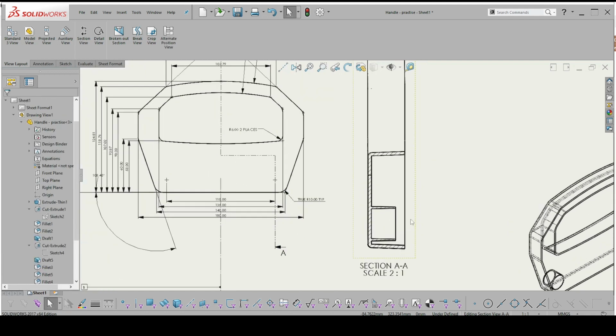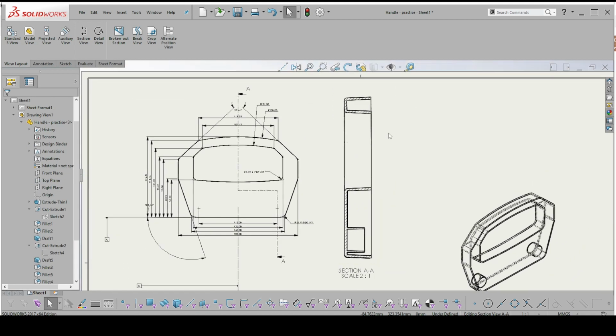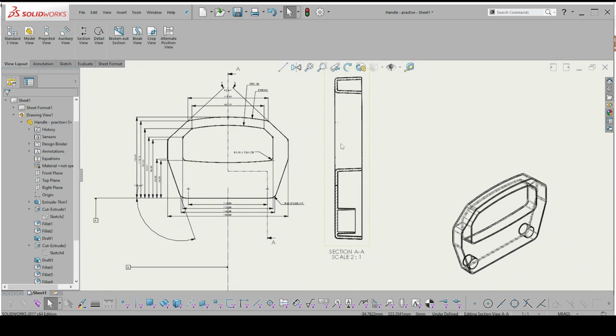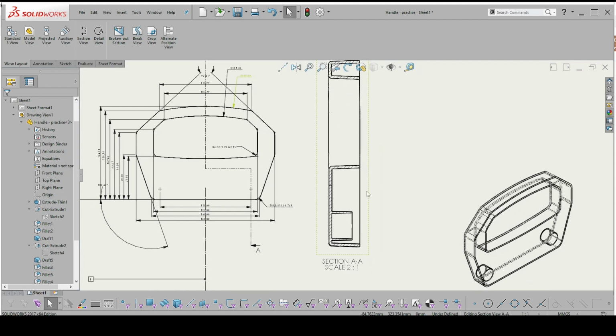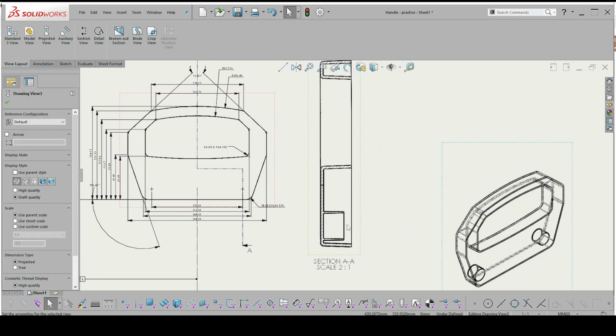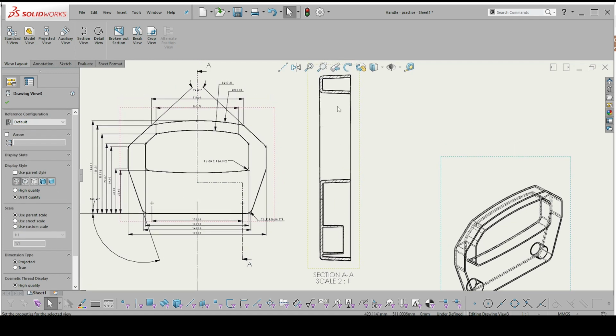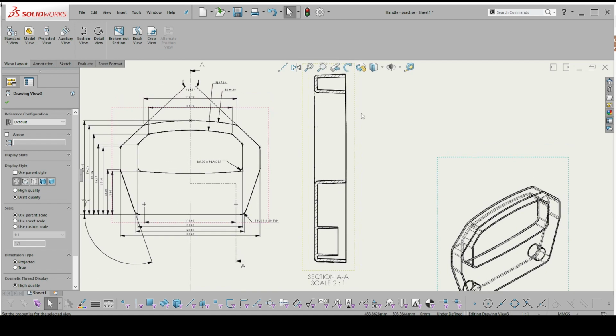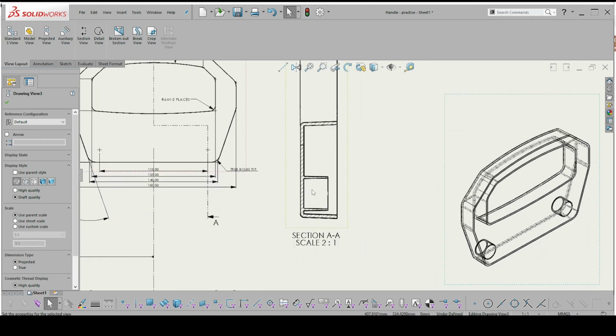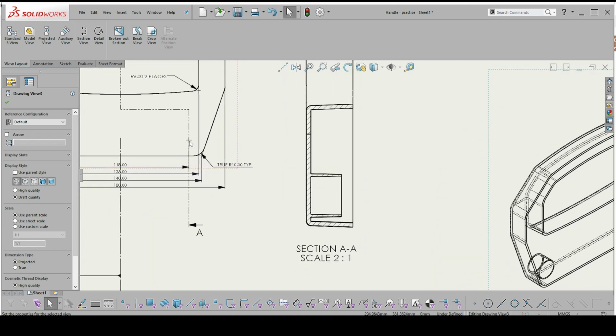Okay, so in this one here, there are a few dimensions I can get out of it. They are these edge fillets here, the center of this boss and its diameter and its root thickness, and that's about it. Oh yes, and the height. So the first thing I want is a center line here.